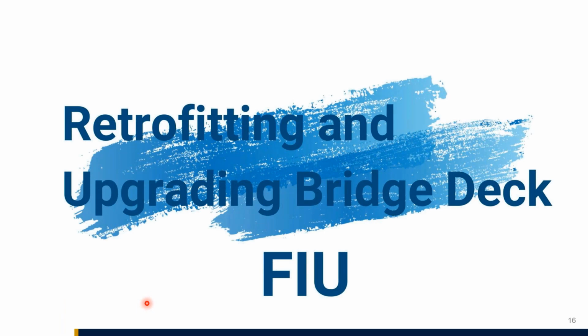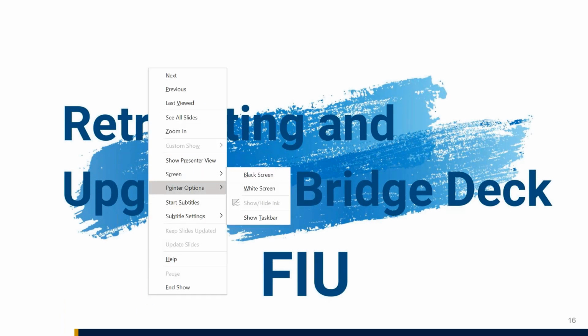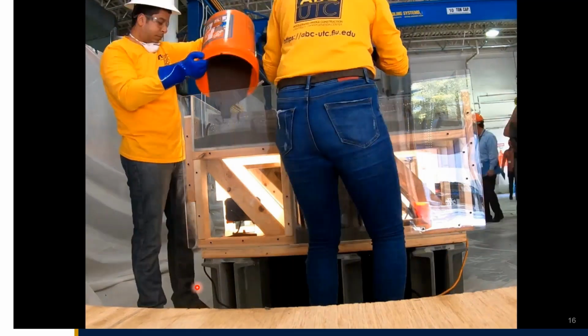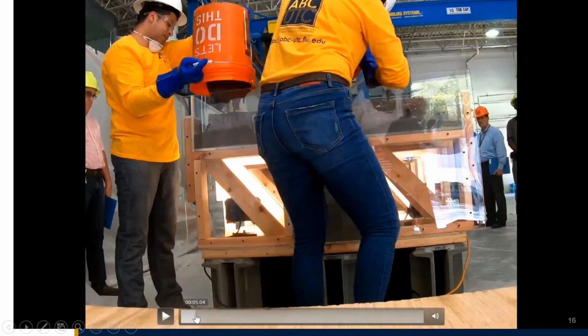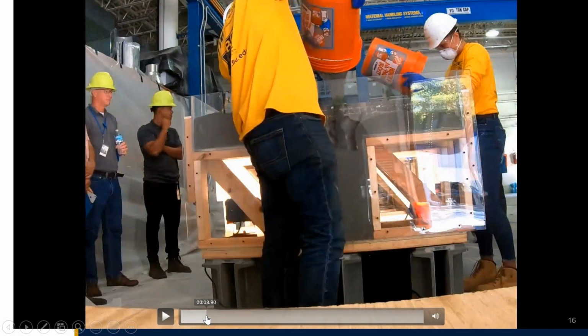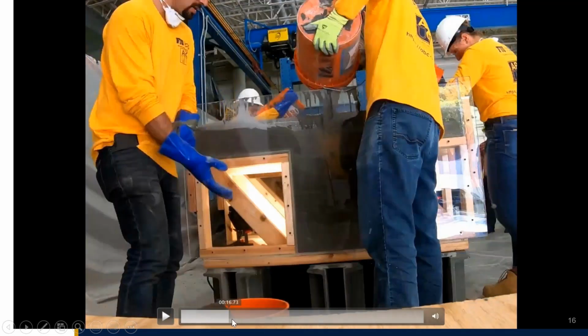And here is, and I'm going to show you, basically we pour the UHPC, and I'm going to show you how fluid this thing was flowing. This is about 1 inch. After the test, there was no honeycomb or anything, because you don't have a coarse aggregate. It's very simple. And here it is. You see how it's flowing very easily.